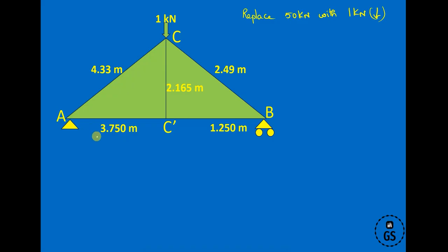So at A we can find out the values. Take moment at point A equal to 0. Making that simplification, we have a beam. RA is here, then RB on the other side, then the load of 1 kilonewton is acting over here. So resolve these forces. Taking moment at point A, it is going to be RB in negative direction,